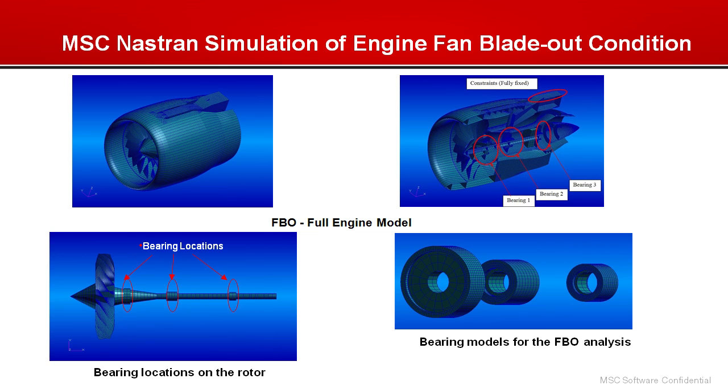The fan blades were constructed by shells with various thicknesses across the width and the length. The rotor was made with a hollow rod with varying cross-section across its length and has a rotational velocity of 4,500 RPM.